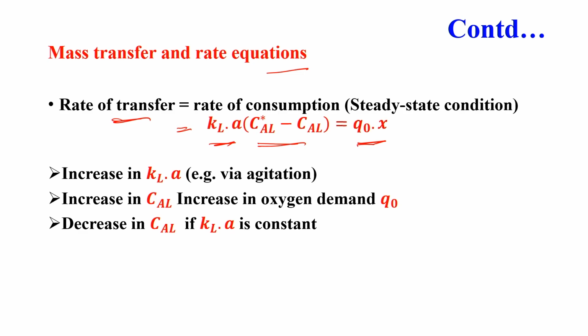Now, how can we increase the rate of transfer? As I discussed briefly, you increase KLA, which can be done by increasing the agitation.